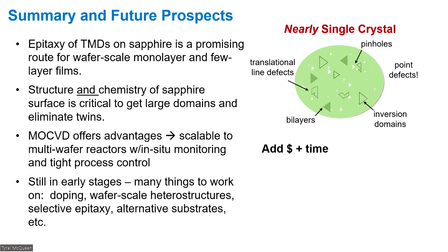Then we pick it up out of the solution and laminate it onto the substrate we're transferring it onto. Sometimes we use an actual laminating process, or if it's small enough, we just press it onto the substrate, but it's fairly straightforward. The challenge is really doing that without introducing bubbles, wrinkles, or other impurities.